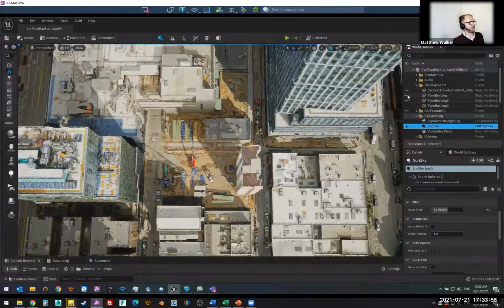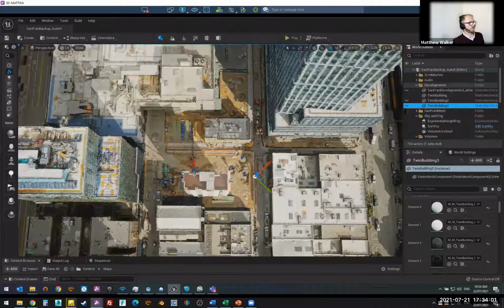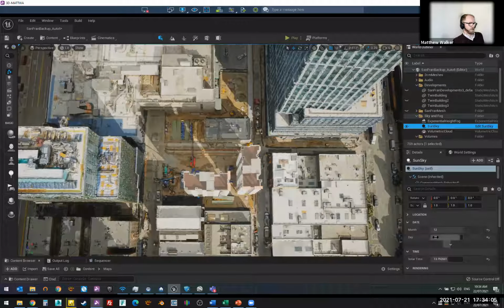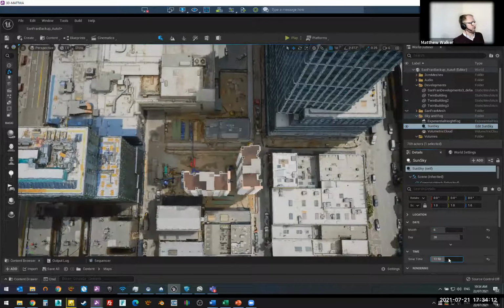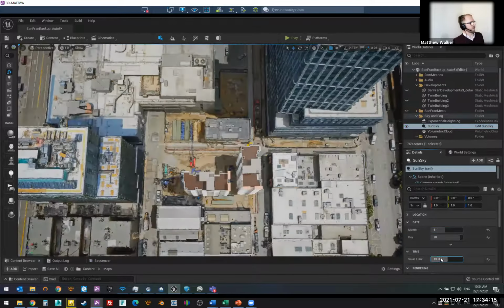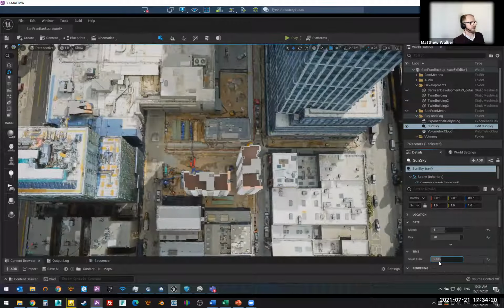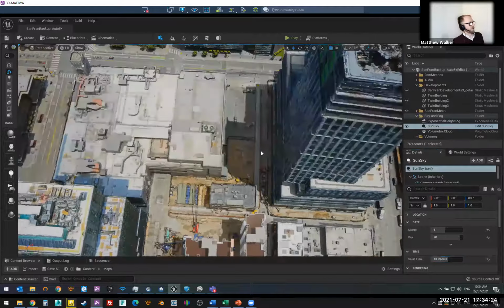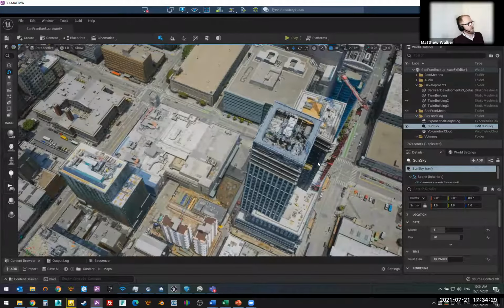We can toggle those on and off and actually see the range of shadows at a range of different times of year as well. So we could jump into, at the moment, we're looking at the 28th of December. Let's come back to maybe June and have a look at the same shadows. You can see that this building actually falls in the shadow of another building quite significantly. Maybe that's a consideration for the site that we're actually proposing. And with enough data, we can absolutely move around and put these buildings in different locations.